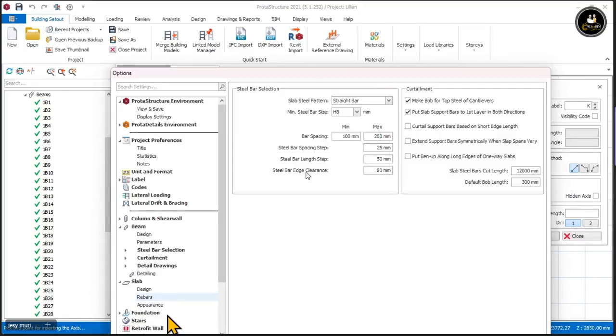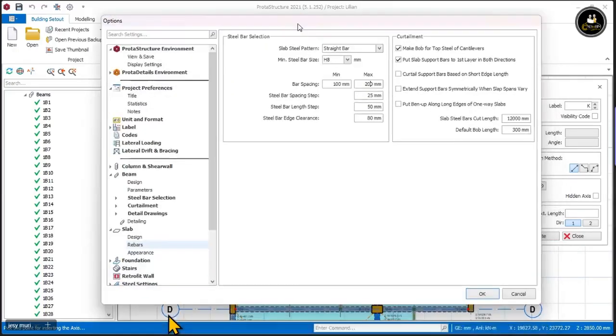And when we are setting this, do you give the concrete cover, or do you let it generate on its own? No, you provide it by default. If you chose your code as BS8110, it will come with 25. Those are the default settings, which are okay. I have not had any problem with the 25. Then you can also check the code that you are using along this column.